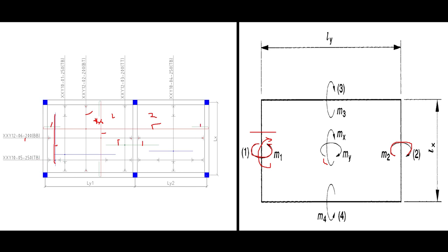If you look at the call out, this is the call out for the bar. You can see it spans from here to here. That is where this one starts to where it ends. Then where this one starts again, it's also continuing from here to here. Then this one continues from here to here, because the reinforcement will not be placed on the beam, so it will not be put in the beam position. So that's why we put this distance. Then it's also going to span this one from here to here. So that is the importance of the distribution reinforcement. The distribution reinforcement is going to be placed in order to balance the detailing.